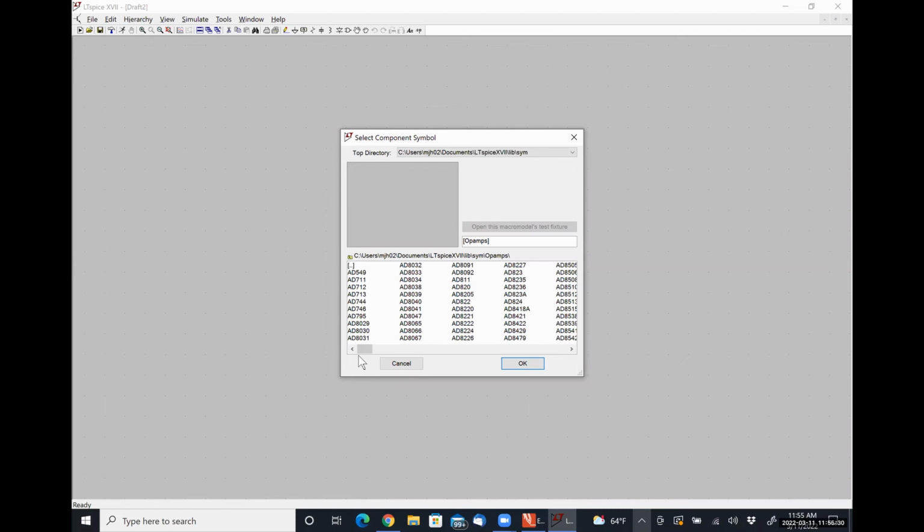On Semiconductor op amps, Texas Instruments op amps, all that kind of good stuff, they aren't in here natively. But if you went to, say, ti.com and looked for a specific op amp, usually somewhere where you can find the data sheet, they will actually also include the SPICE model as well, so that you can import the characteristics of their op amps and other microelectronic circuits for use in your simulation. Now that can be a bit of a pain trying to hunt down a SPICE model for a particular thing.